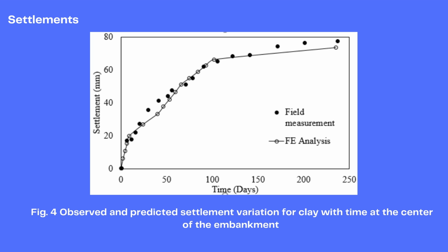Also, this standard specifies allowable differential settlement at the time of the design and handover to be 0.5% over 5 meters for sealed asphalt surfaces. So in this case, the rate of embankment settlement after construction is about 23.7 millimeters per year.